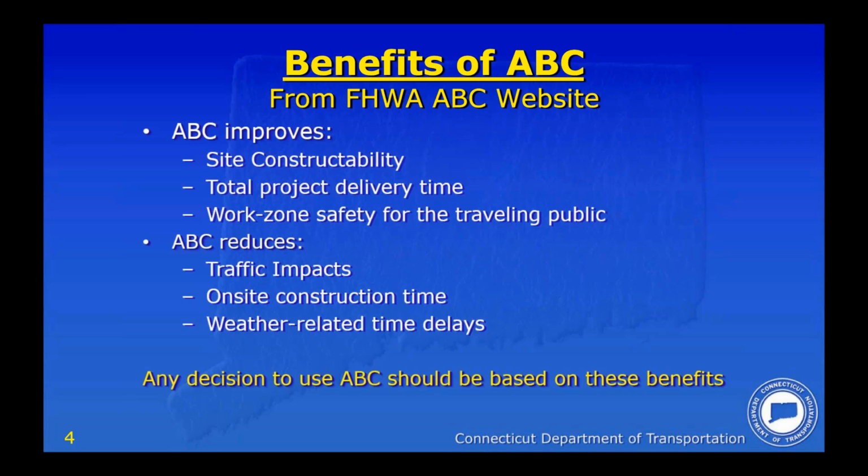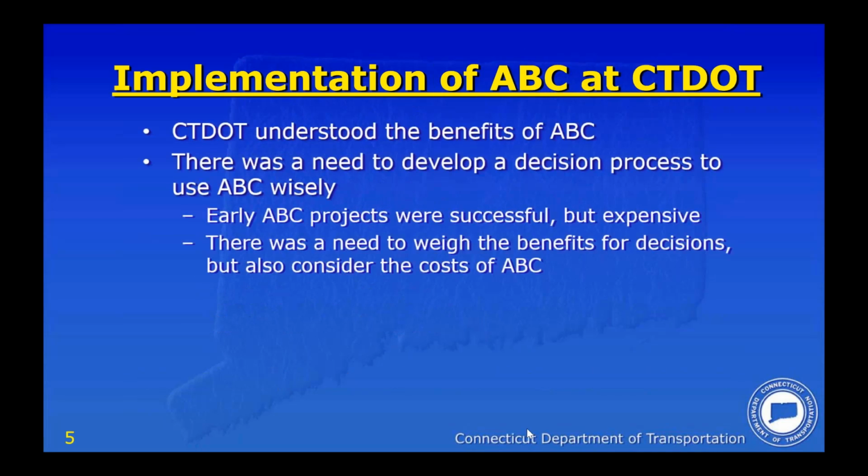Overall, we found traffic impacts are reduced. There may be more extreme short-term traffic impacts with ABC, but overall, they're generally reduced. Certainly on-site construction time is reduced for standalone bridge projects. And weather-related time delays can be more easily mitigated.